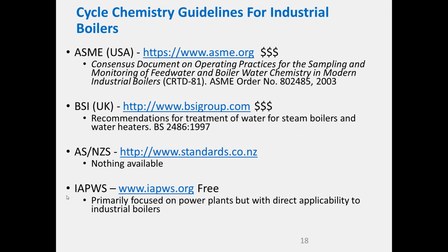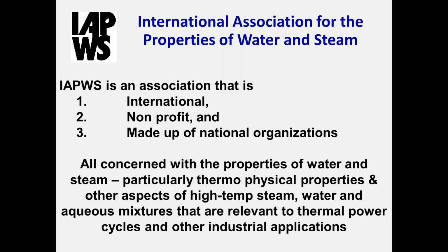And then there's also these IAPWS guidelines from the International Association for the Properties of Water and Steam. These are free. These are primarily focused on power plants, but they do have direct applicability to industrial boilers, and there is some discussion around whether IAPWS should produce an industrial boiler guideline as well. So just quickly on that, if you've ever used a steam table, you would have used some IAPWS technology. It's a non-profit association made up of national organisations. New Zealand's a member. I'm heavily involved in it, and all very interested in the thermophysical properties of water and steam, particularly for thermal power plants and industrial applications.